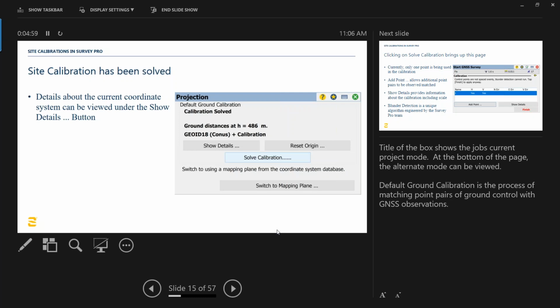Okay, my point is that you always need to correct for a shift. So you have to do a vertical calibration on at least 1 or 2 points to correct for the shift. My point is that with modern geoid models, they already have that tilt dialed in. So if you go ahead and do 3 or more points for your vertical calibration, you're essentially trying to measure the tilt better than the NGS's $100 million gravity program has been able to determine the tilt, right?